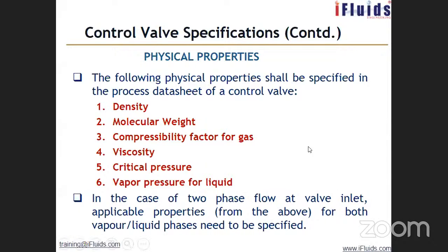In case of two-phase flow, valve inlet applicable properties. Usually two-phase flow handling by the valve is somewhat a typical difficult situation, I would say. So when you have two-phase at the valve inlet, you have to tell the instrumentation engineer and the valve vendor about the two-phase characteristics.